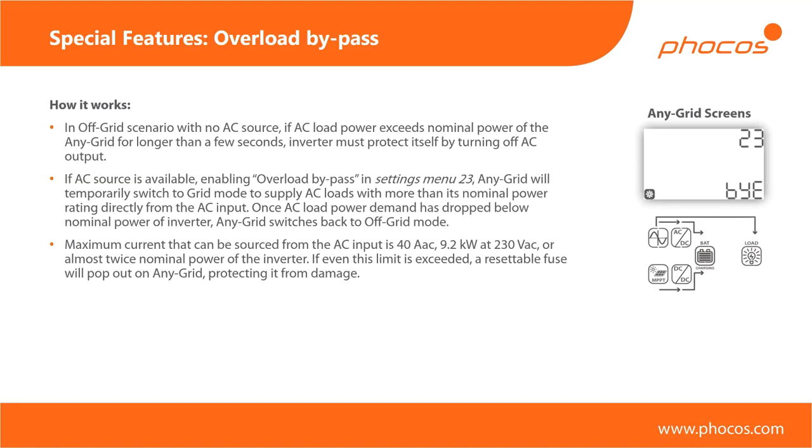So there's really a lot of even market leaders out there which have very slow systems in the sense that if you can imagine, for example, if you're cooking something and you have a heating element which will turn on and off maybe every second or every few seconds, this type of system will not be able to cope with that load. Sometimes it will accidentally inject into the grid because, well, your load has turned off and it's trying to provide 2 kilowatts now. And the opposite will happen as well. You're consuming 2 kilowatts and the system just hasn't caught up. It's not taking the 2 kilowatts out of the battery, but instead it's coming out of the grid.